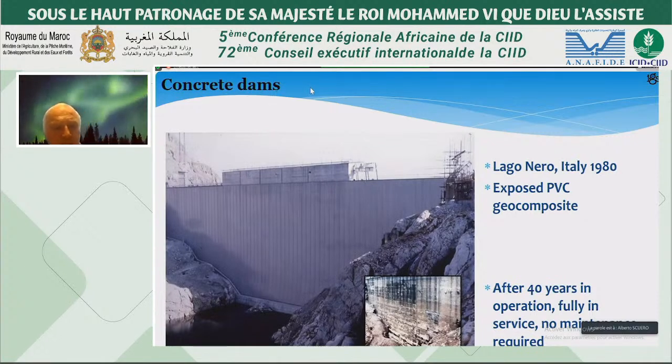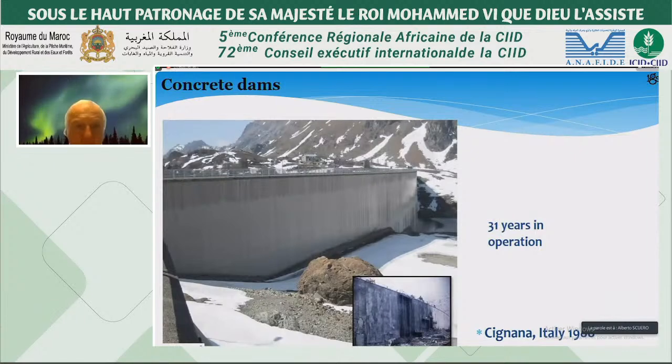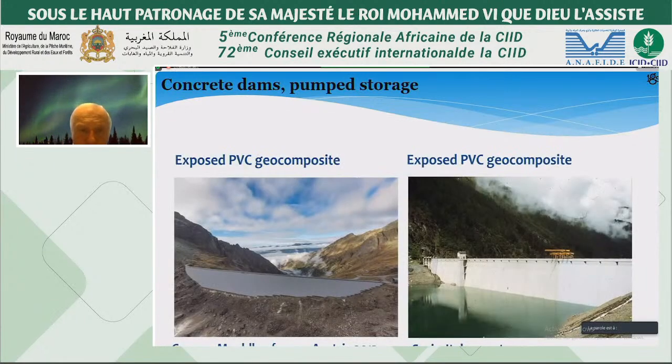We have some cases here of concrete dams. Lago Nero in Italy was lined with exposed PVC geocomposite in 1980. After 40 years in operation, it is still in full service and no maintenance required. Cignana Dam in Italy, 31 years in operation. Or this dam in Austria and in Italy, which are part of pump storage schemes with exposed PVC geocomposite.